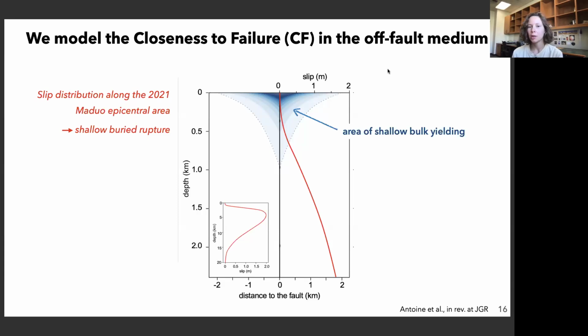So it means that it's not only possible, but it is very highly likely that that shallow area above the fault yielded during the coseismic rupture. The scale of the yielding here is quite consistent with what we have seen in the observations, though it is very susceptible to change if you calibrate the model using the right shear bulk modulus curve and how it evolves with the depth.